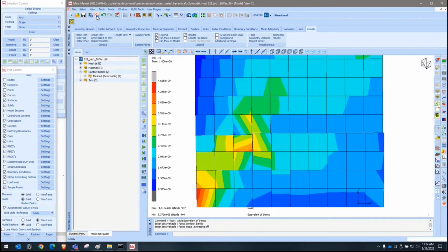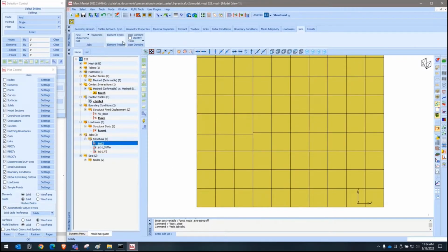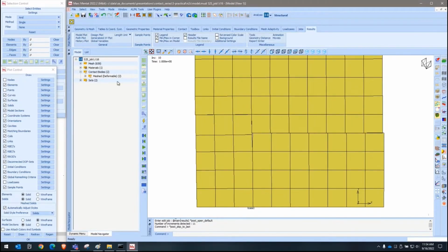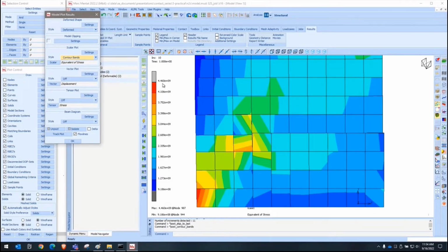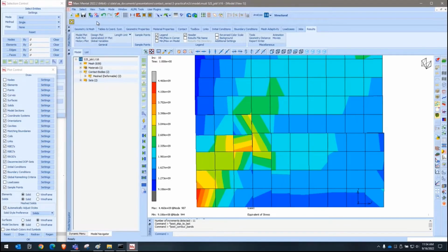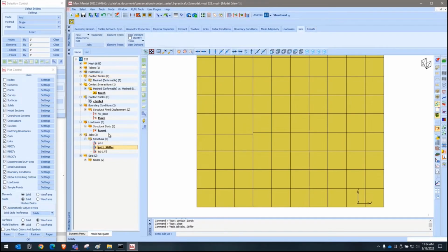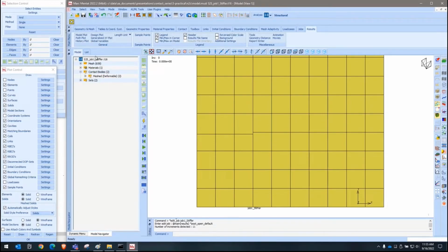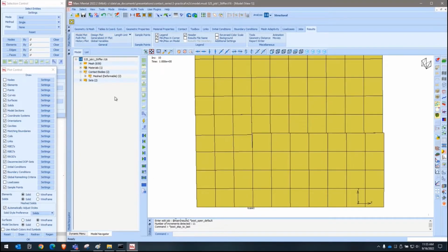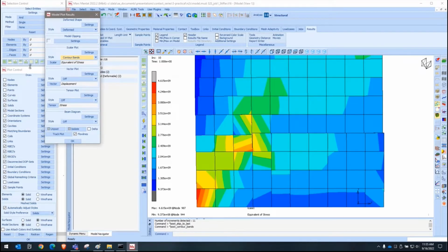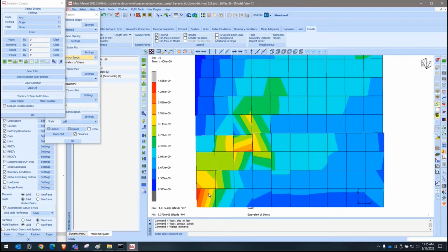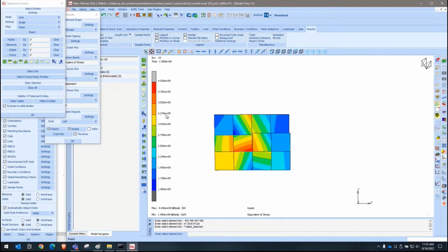So remember that number. We open the original model, go to the same step, and we activate the same result, 4.46. So it's similar, not the same, but it actually looks like it's in a different region. Let's rather do this. Open the stiffest one again, and we'll only plot the elements in that region. Okay, so just over 4 gigapascal in that region.